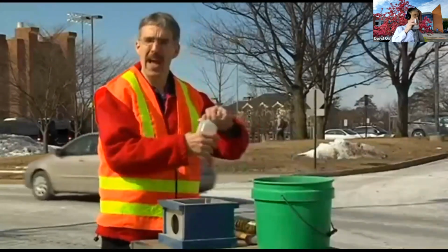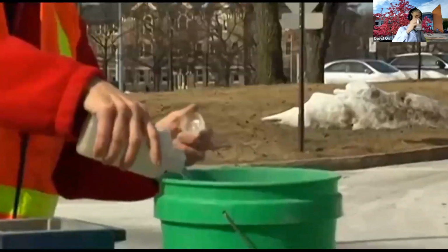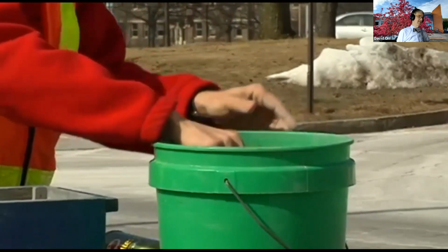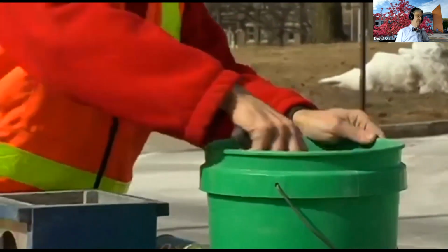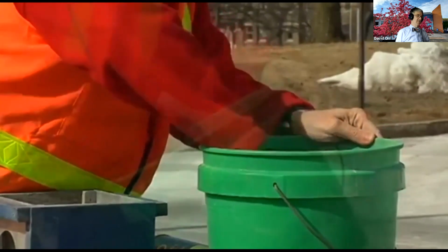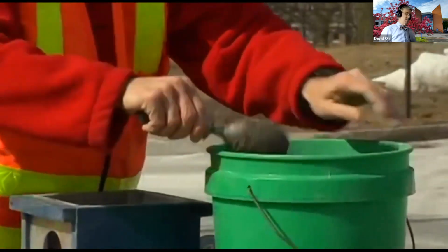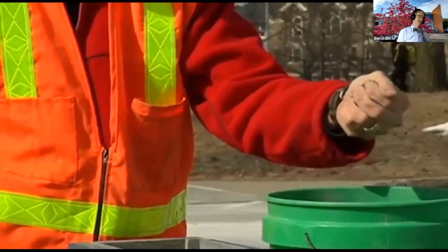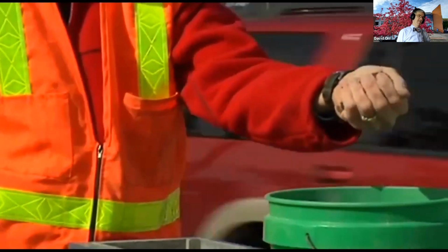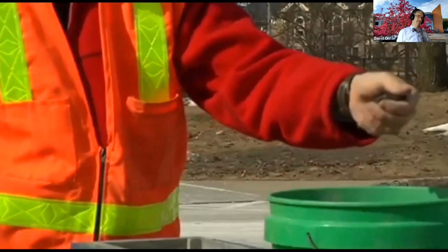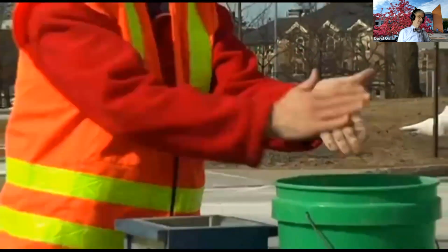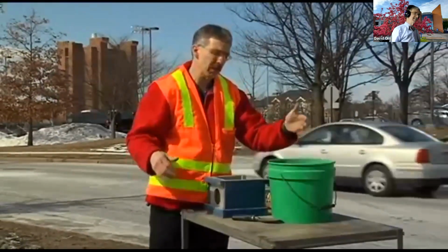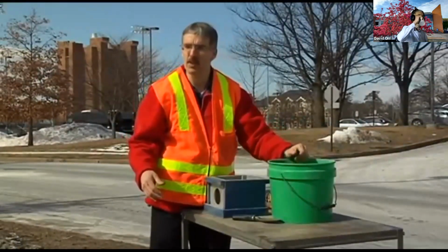Well, how much moisture we add can be calculated, but as a good rule of thumb, you want to have enough moisture in it where it will hold a cast, but not so much moisture that when you squeeze it, it comes off on your hand. So now we've added some water to it, and we squeeze, and as you can see, it's just starting to hold a cast, and there's not water coming off on my hands. Okay, so that's pretty good. Again, we could test for this in the lab, and there are tests that we recommend people do, but as a minimum, would you at least give the gravel a little bit of a squeeze?